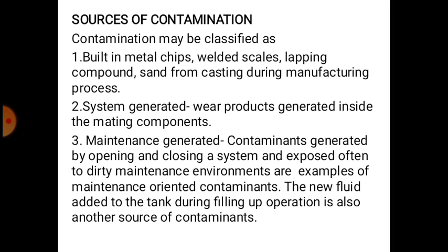Some are maintenance generated: contaminants generated by opening and closing of a system and exposure often to dirty maintenance environments are examples of maintenance oriented contaminations. The new fluid added to the tank during filling up operation is also another source of contamination.